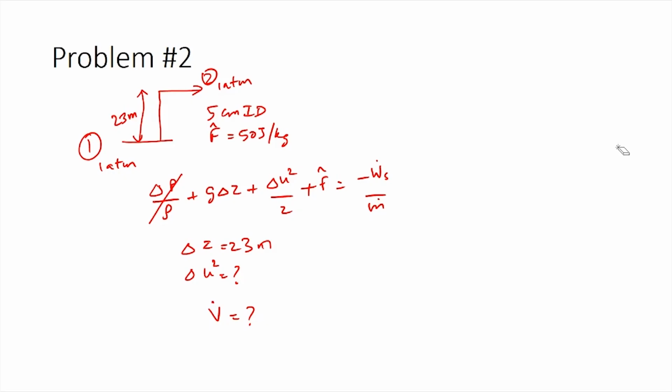As we have assumed that the volumes are additive, we know the total volume of the final 60% mixture and the initial volume of the 95% glycerol mixture. So, we can calculate the volume of the 35% glycerol mixture using these two values. So, the volume of 35% glycerol mixture would be 2610 minus 1000, giving a value of 1610 liters. So, this is the volume which we are adding. We know that this is being added over a period of 13 minutes, from which we can calculate the volumetric flow rate. From the volumetric flow rate, we can calculate the linear velocity by dividing it by the cross sectional area. So, linear velocity at point 2 would be equal to